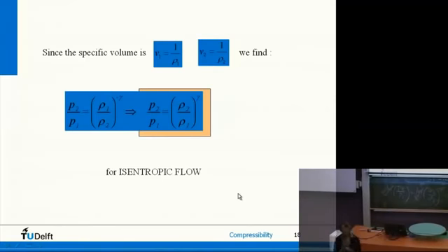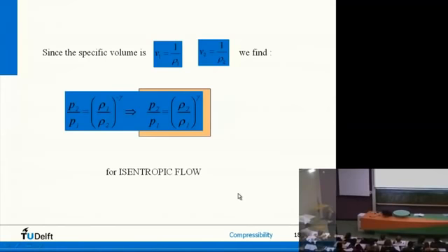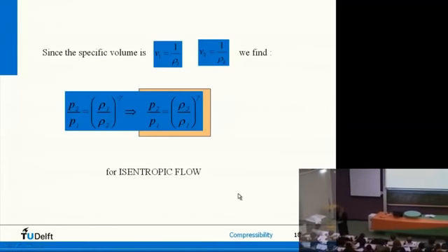Please remember this is an isentropic flow relation. So if you add heat or subtract heat, it's not true anymore. But for aircraft, flow around aircraft, this is perfectly usable everywhere outside the boundary layer. Also, friction effects should not be dominant. So this is one form of the isentropic flow relations. So relating pressures in 2 points and densities in 2 points.